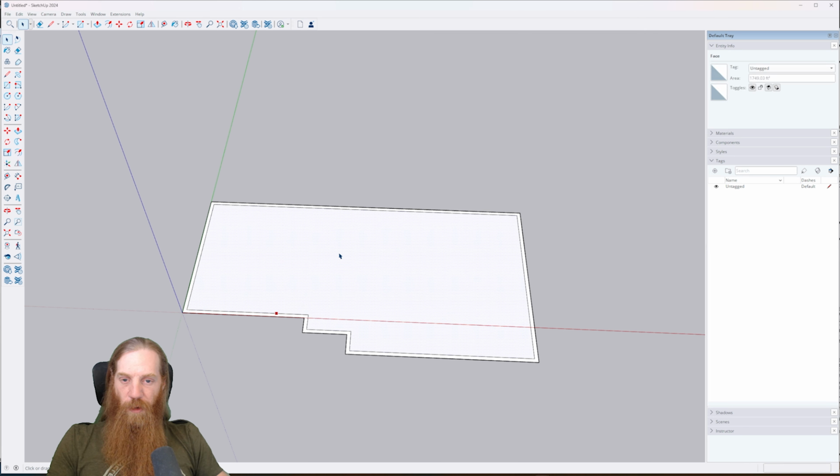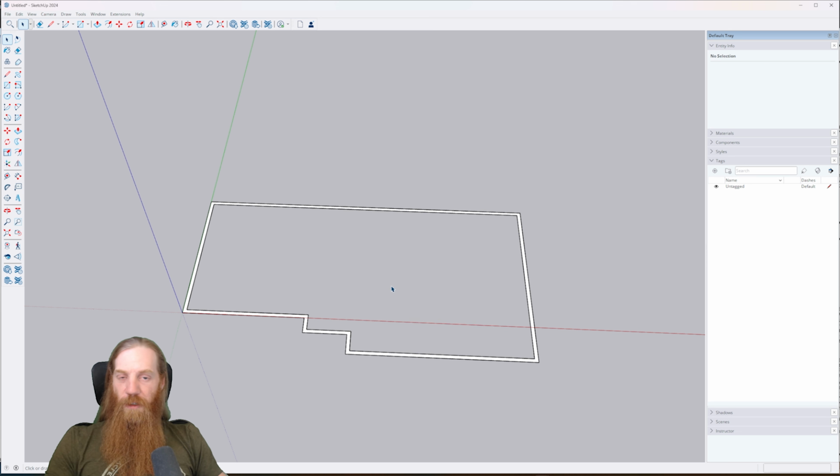What I will then do is press spacebar to get my select cursor. I click anywhere on this interior section and it'll select it. You know it's selected because it'll have the blue dots all over it, or it'll be slightly shaded blue. They look like little dots if you look closely. So you select it and then just hit delete, and it's going to delete that whole interior section. So now we have what is essentially a cross section of our foundation wall. Now, in order to actually turn that into a foundation wall, we're going to wait on the, well, let me think.